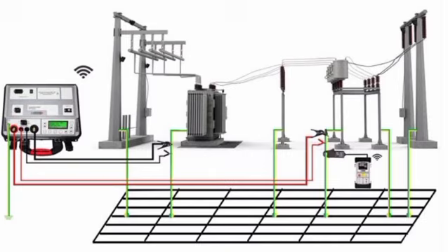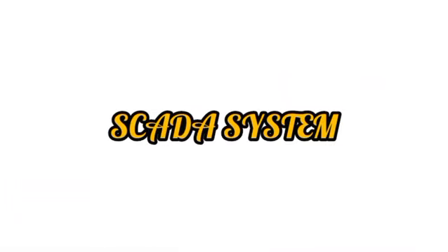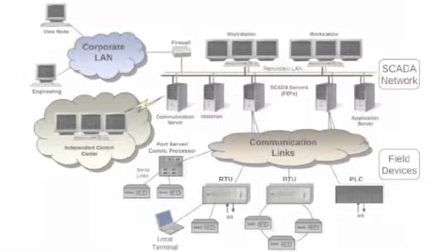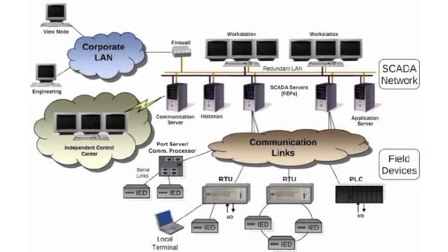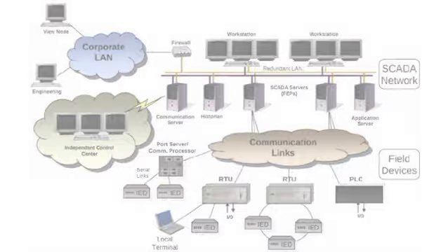Ensures personnel safety and equipment protection. Grid design follows IEEE 80 or equivalent standards, includes earth mat, rods, conductors, and pits. SCADA system. Supervisory control and data acquisition system for remote monitoring, interfaces with all digital protective devices, IEDs, enables real-time fault detection, load analysis, and remote control.